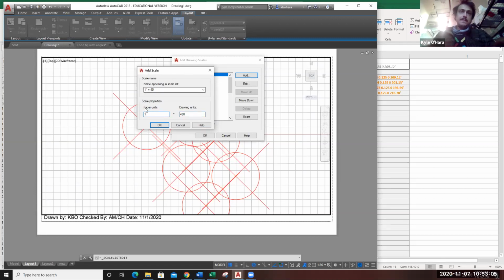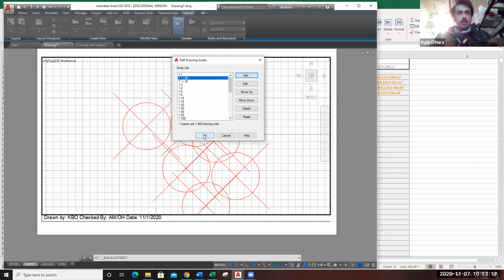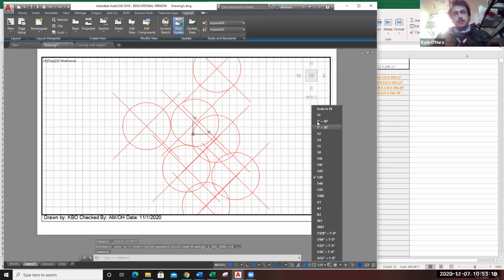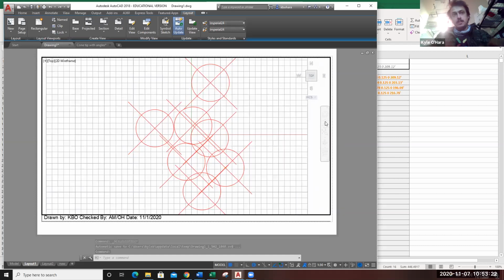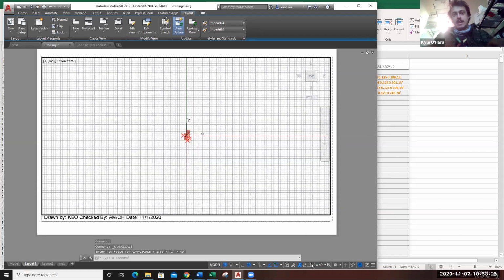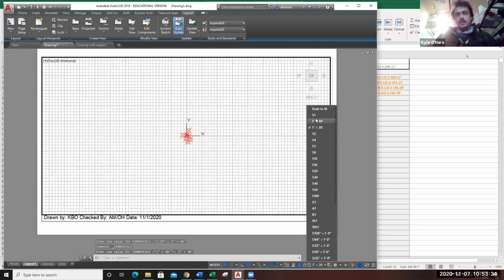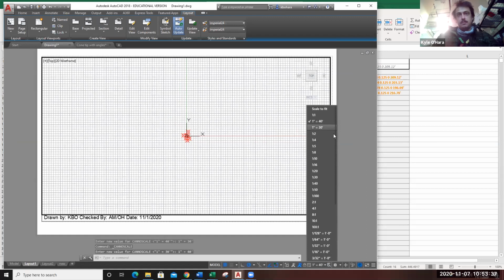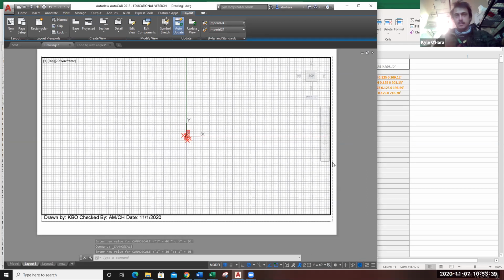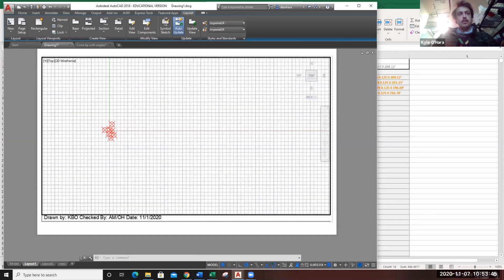So yep, that's it. You just have to multiply whatever your value in feet is by 12 to get the value in inches. And then it'll show up. And now here at the bottom, we can open up our tab and we can have the appropriate scale. So you might want to make one of these for 30 feet, 1 to 40, and all the ones between 10 and 60. And you'll just have to play with these to figure out which works best for your project.